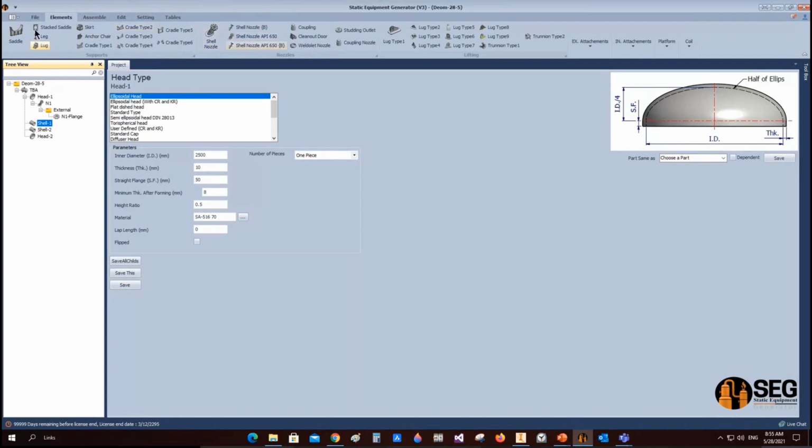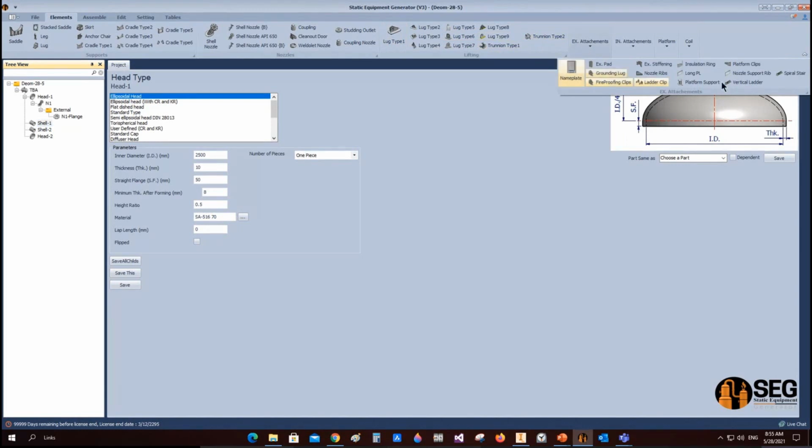clean-outs, well-lit stud outlet coupling, different types of lifting lugs which we discussed on the slide, external attachments like nameplate, external bands, ground lug, fireproofing, stiffening rings, ribs for nozzles, ladders and insulation rings, many different attachments, and for the internals, impingement baffles, deflectors, longitudinal plates, stiffening rings, trays, baffles, vortex breaker, pass partitions, platforms, and coils. Okay, now let's add a nozzle with internal projection.